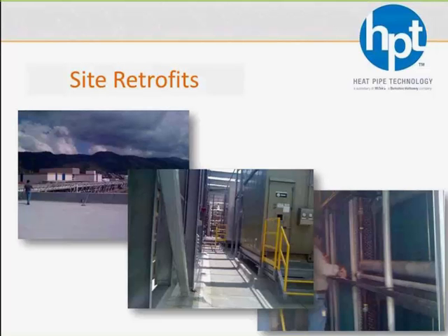We can install the pre-cool in one split and the reheat in the other split, have it go out to the job site, put the air handler together, then we'll come out there and circuit it up and charge it and get it together for you.